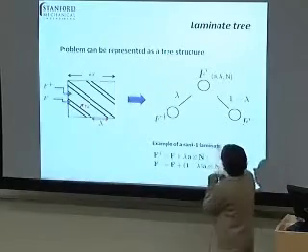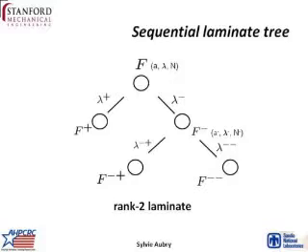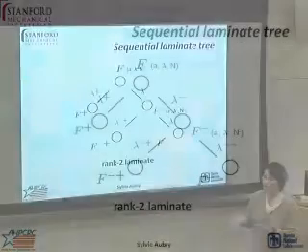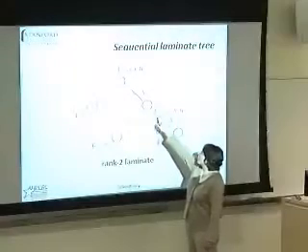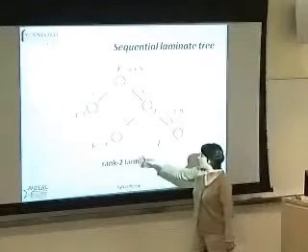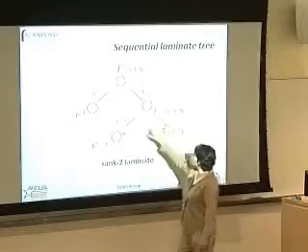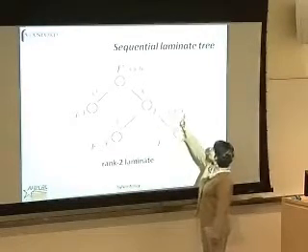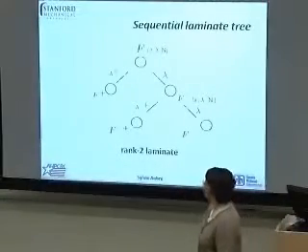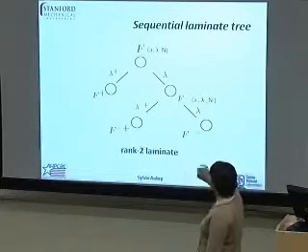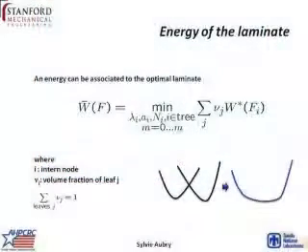So if you do that, well, you can do something a bit more complicated. Now, let's say you want to find the minimum structure. So how about replacing F minus by 2 other deformation gradients, F minus plus and F minus minus, with 2 other proportions, and you have a set of other parameters. And then maybe this structure will minimize the energy even better. So from these deformation gradients, all these F's that you get, you can define another energy.